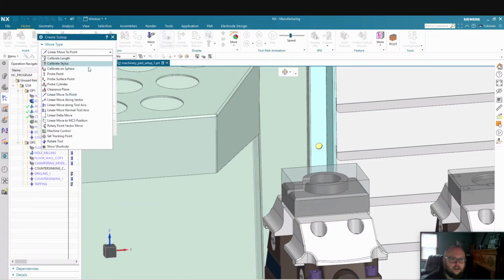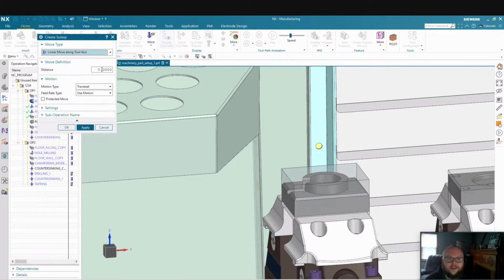And I'm going to go ahead and just to kind of how this works out, I'll make another motion here. I'm going to use the linear move along 2 axis and location. We're kind of working in a sequential order here. So currently I'm 3 inches. Does the audio sound right to you? So I'm going to move -2 inches in Z.